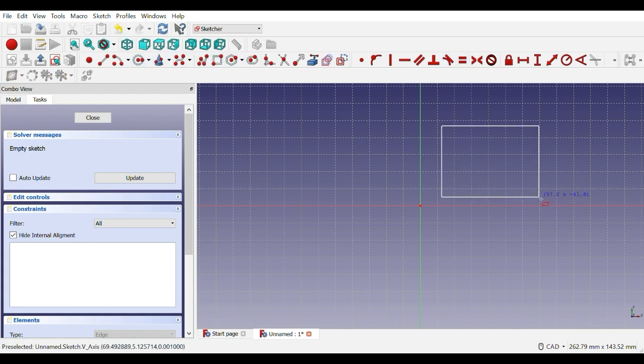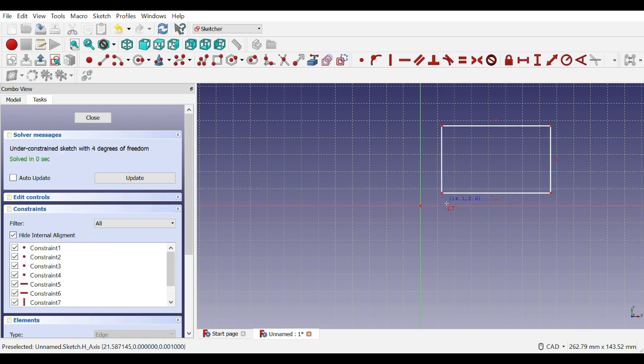Okay, now we're going to create a basic shape. Let's start with a square. Notice I'm doing it in the XY positive quadrant because CNC machines cut over here. Okay, let's put a couple circles into this square, and I want to show you the power of using FreeCAD. FreeCAD lets you constrain things and base things on other things. So for example, if I want all of these circles to be the same size, I click the circle radius, click here, and I will say 4 millimeters.